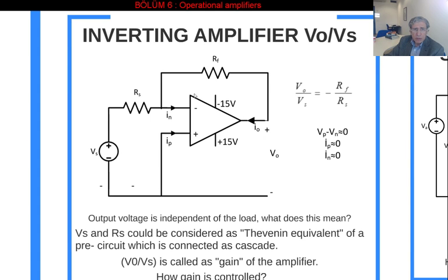So what we have here is our operational amplifier, the definition relation is given here, and the plus terminal is connected to the ground, which means this voltage is 0. The negative terminal of my operational amplifier is connected to an independent voltage source in series, Vs. You might consider this circuit here as a Thevenin equivalent circuit of a given circuit. So you might consider two-stage cascade connected networks or circuits connected together.